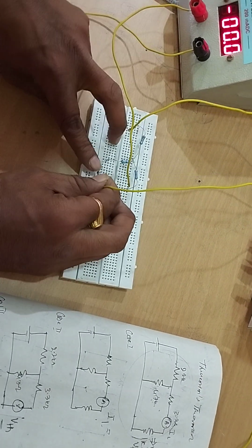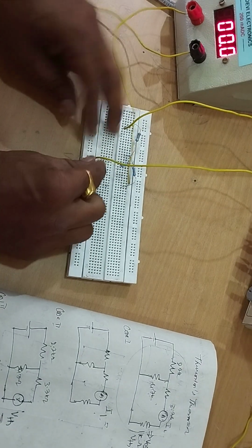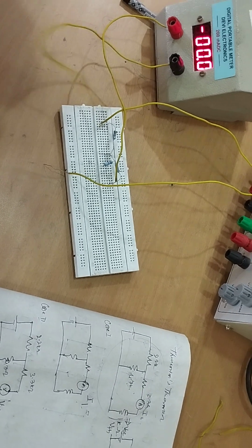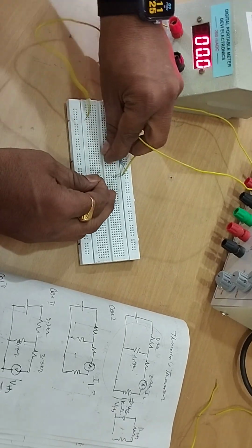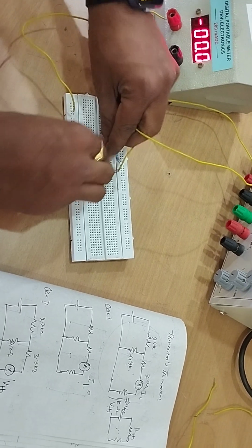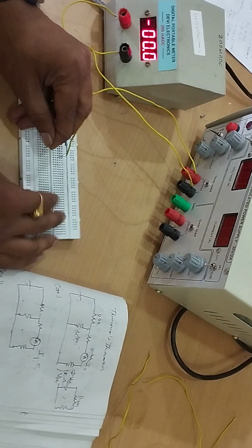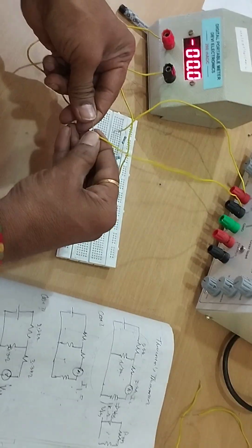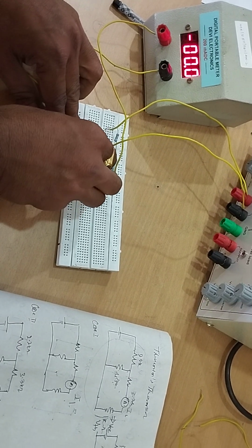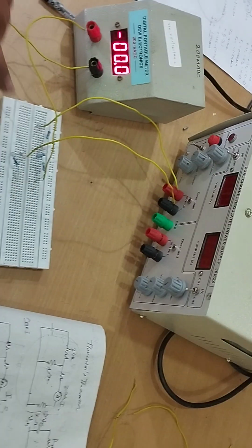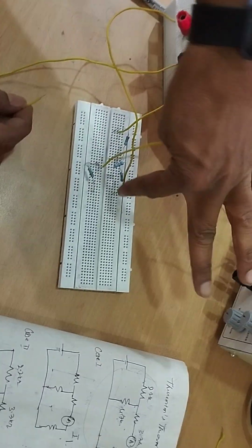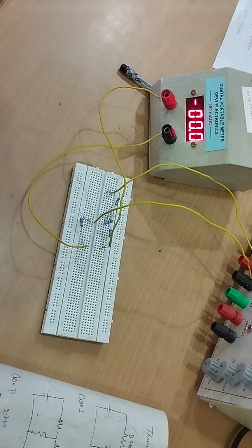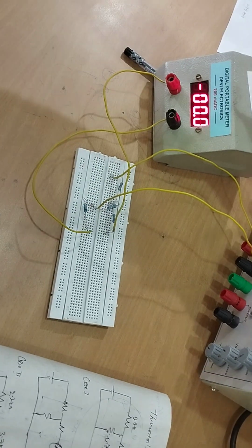Now it is our task to place the ammeter. See that the terminals are properly connected in the same vertical line where we are connecting here. So this is the same vertical line. We will keep the first terminal of the load resistor somewhere else like this to make the connections for the ammeter, and ground is placed in this section. The ammeter negative is connected to the 1K's first end, the positive terminal is taken here. This makes the connection.